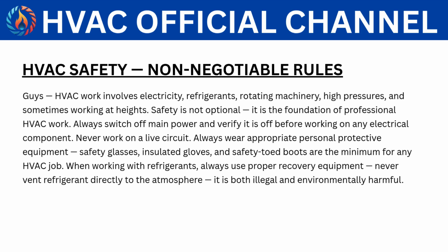HVAC safety, non-negotiable rules. Guys, HVAC work involves electricity, refrigerants, rotating machinery, high pressures, and sometimes working at heights. Safety is not optional. It is the foundation of professional HVAC work. Always switch off main power and verify it is off before working on any electrical component. Never work on a live circuit.